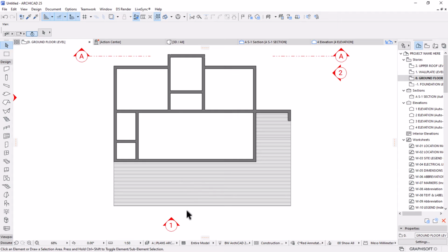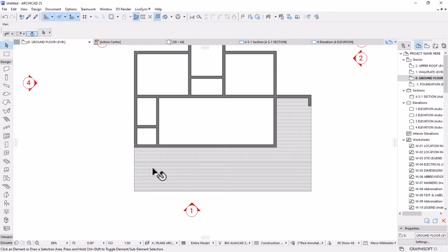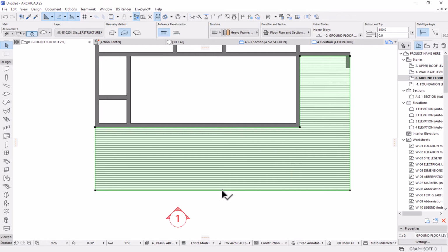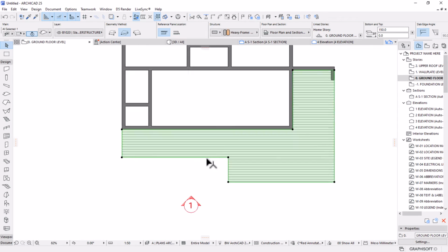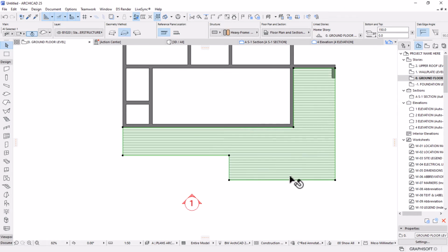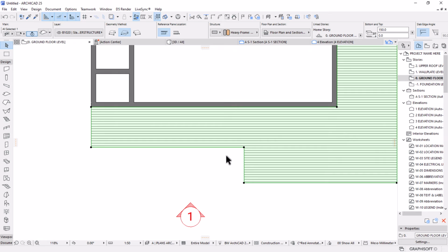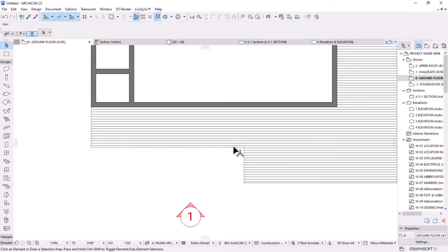So obviously we now have everything in terms of our sketch. Obviously I have a planter here that will determine this. This planter is going to be positioned roughly on the center of this. So I'm going to select this and add a point on the midpoint of the slab. Then select this edge on the side, then use offset edge and move back by 1.5. That will create a section for our planter. Okay, this is a section for our planter.